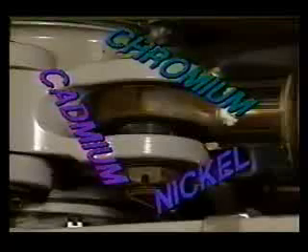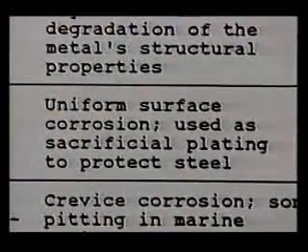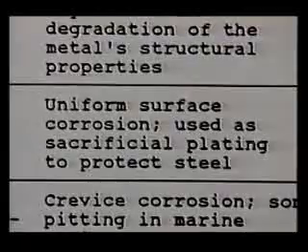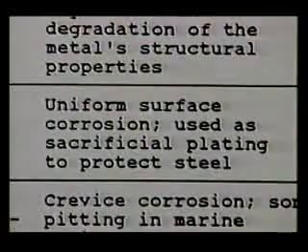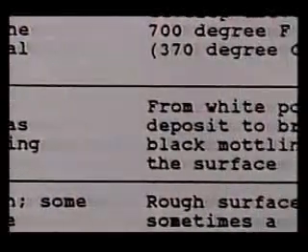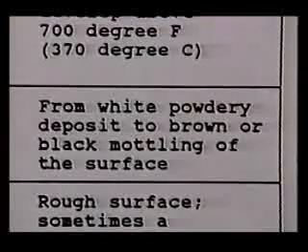Several metals are used to plate steels used in aircraft construction. Cadmium, for example, is a sacrificial coating. It corrodes, so the metal underneath doesn't. Cadmium is used to coat steel parts and to provide a compatible surface when a steel part is in contact with other materials. When the cadmium coating is intact, it will have a yellow appearance. When cadmium is worn away, exposing the metal underneath to the environment, a uniform reddish-brown stain often appears, which is the beginning of rust in the steel.